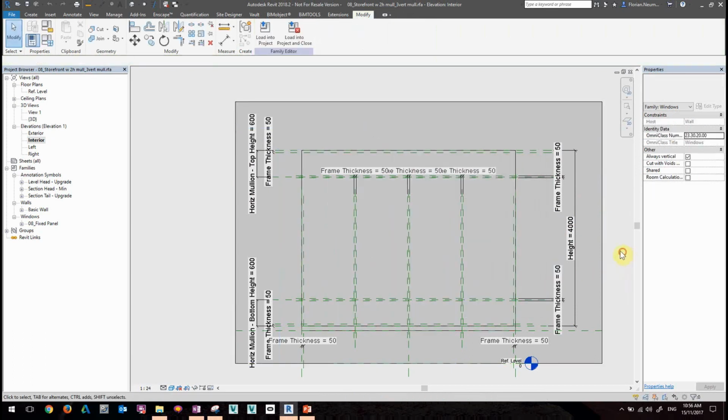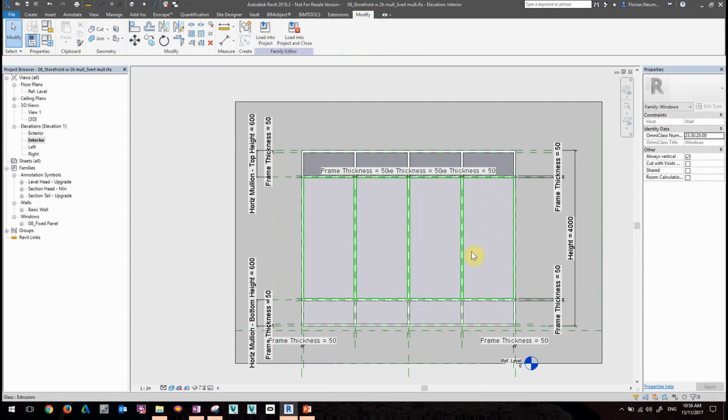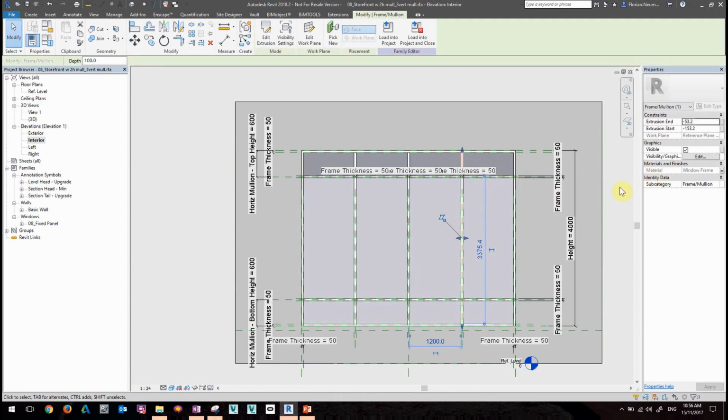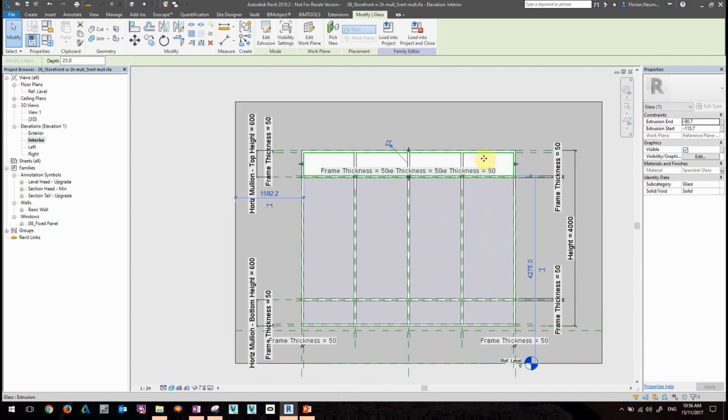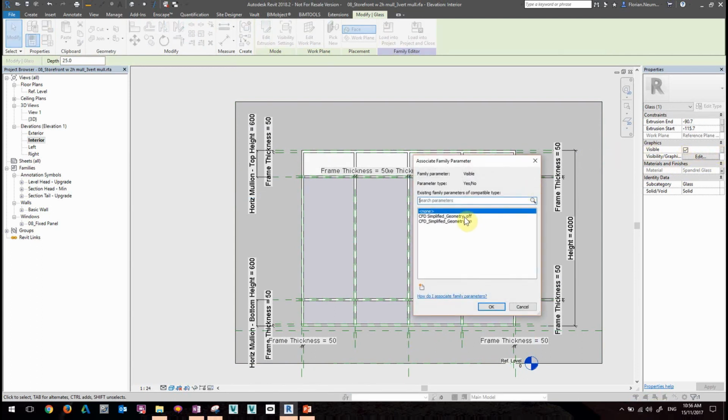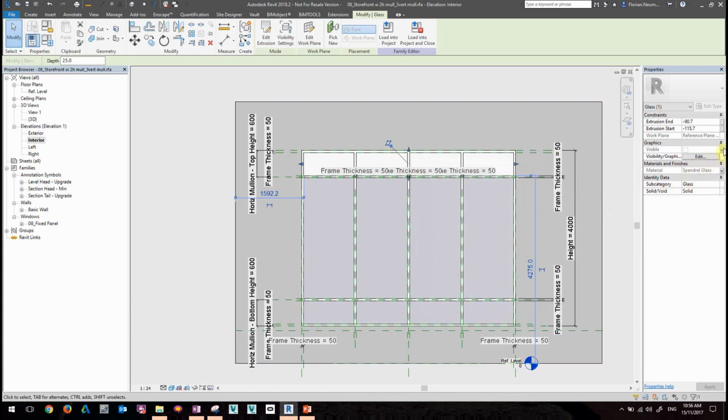So the other geometry, I may quickly select it and delete this here. The other geometry I can also hook up with my other parameter, my visibility. For instance, I would connect this now with CFD simplified geometry turned off. When I select this now, we see there are equal signs on the side, and when I go back into my family and switch off, this geometry is then not shown, if you want to go there for that.